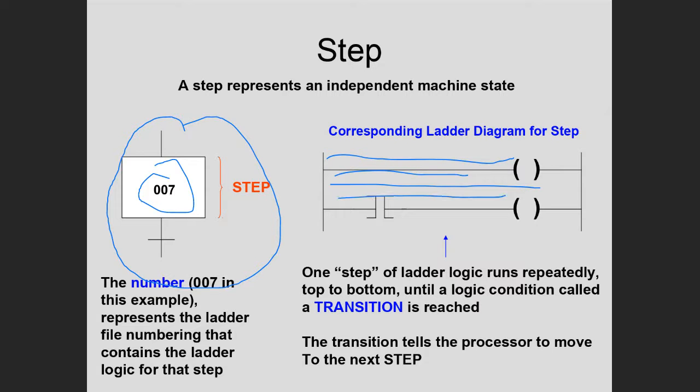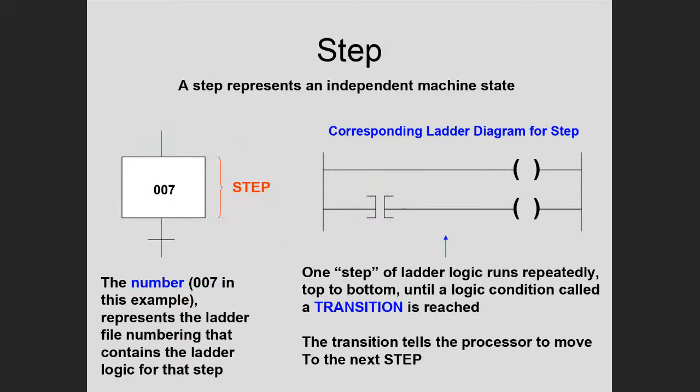Each step does just one or two things at most, so you'll have the rungs to do that. So I don't have a lot here. This one is not conditional, so the minute this rung goes true, it's going to read the switches. And so you've got these rungs in here for this step right here. You've got that program. Well, once you get it programmed, then you would double click on this line right here,